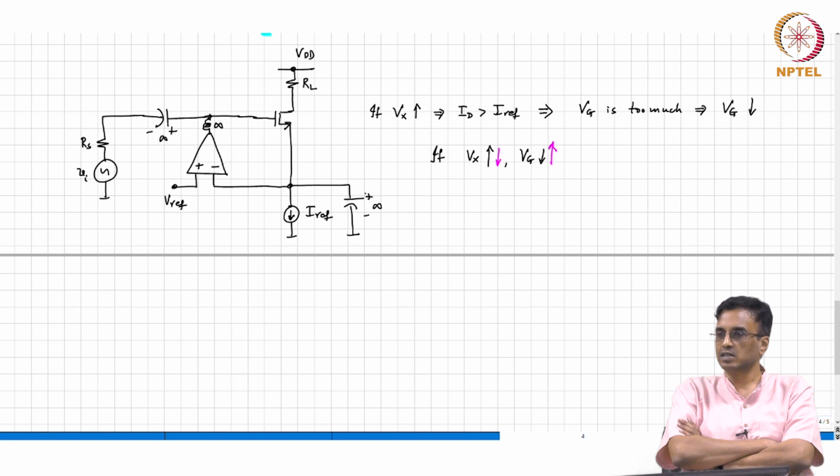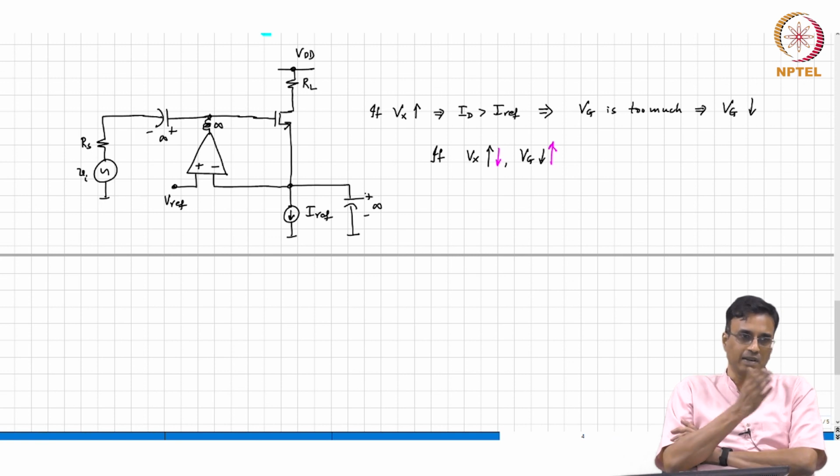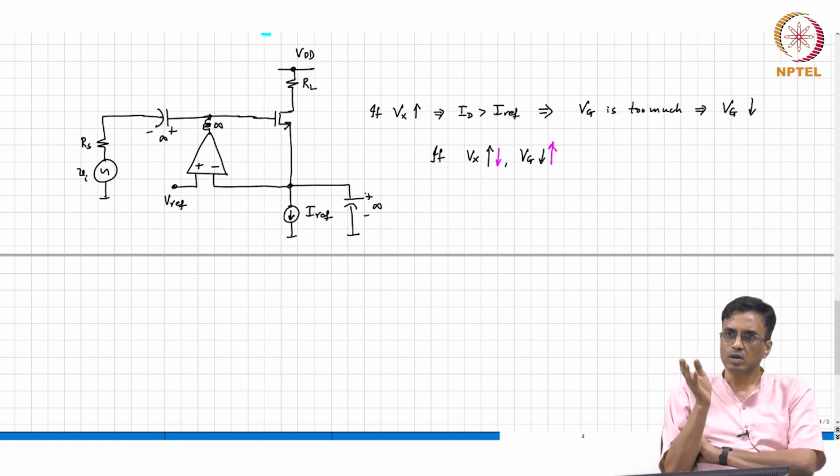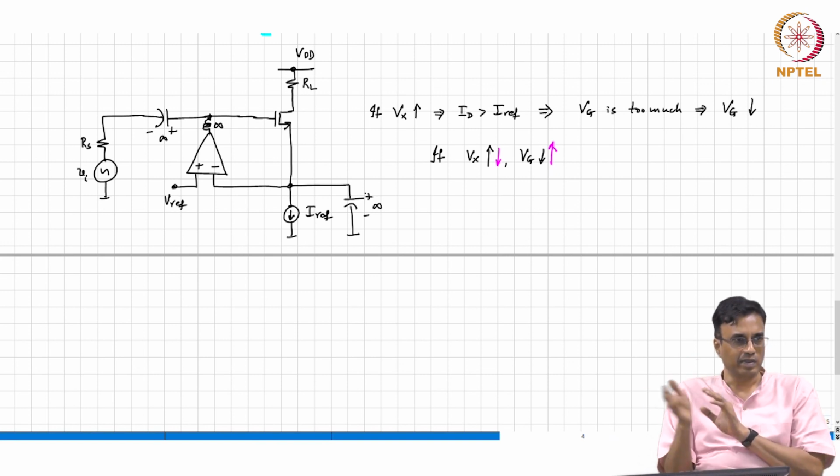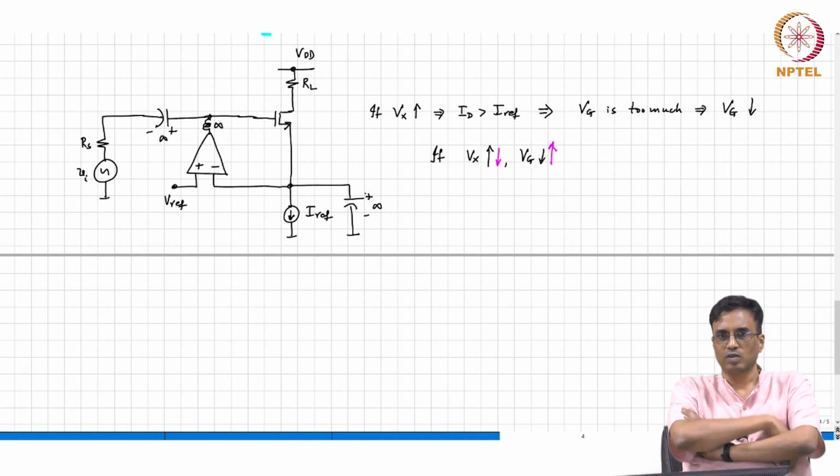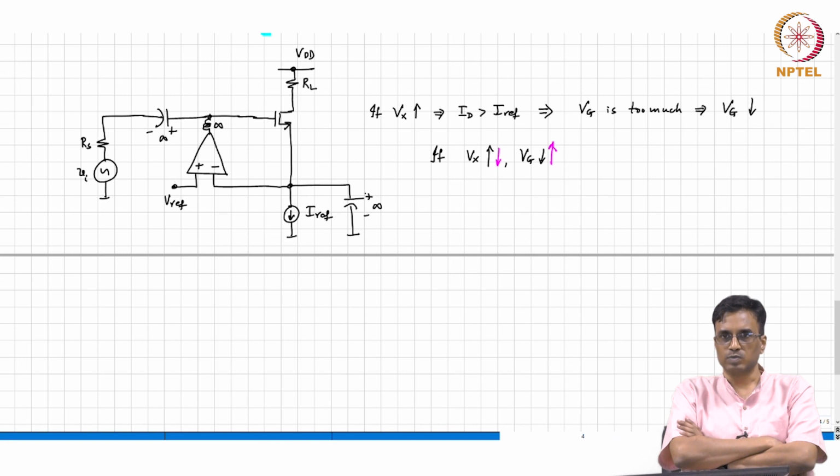Then there will be one condition for the transistor entering the edge of the triode region. There will be another condition that will push the transistor into cutoff, and you basically go, the minimum of those two amplitudes is what the maximum input swing you can tolerate will be. Is that clear, folks?